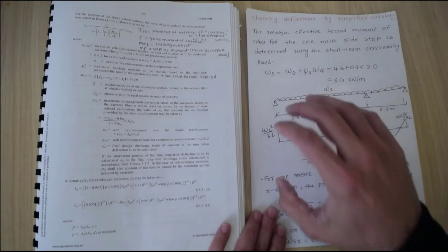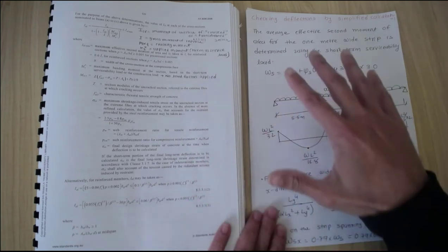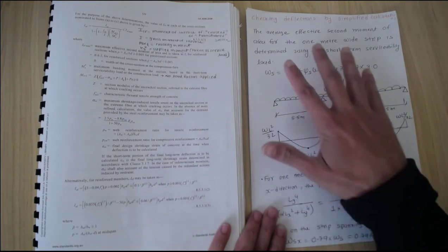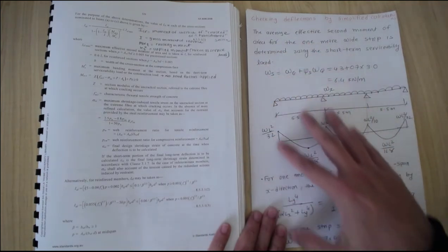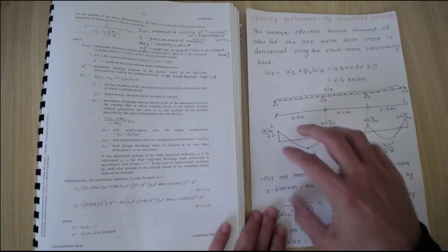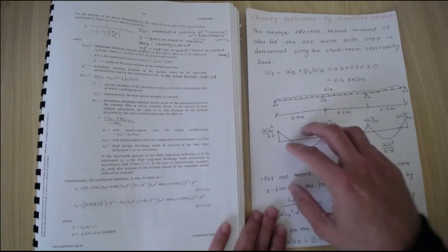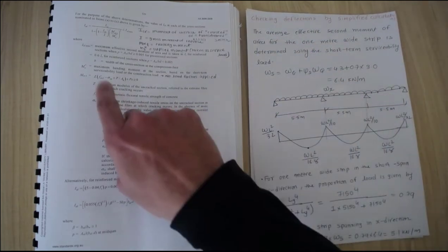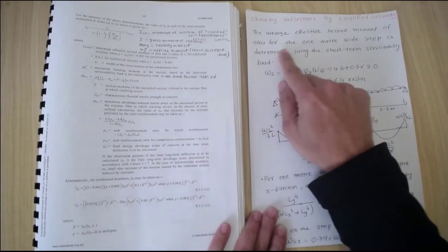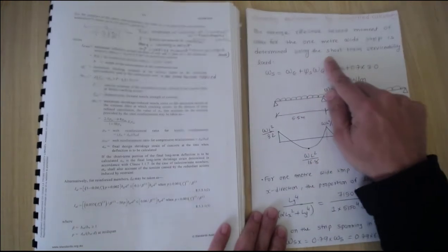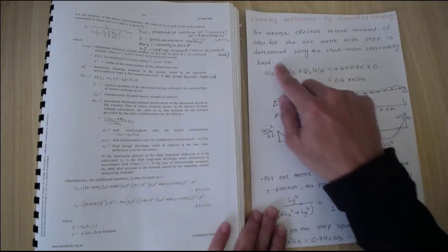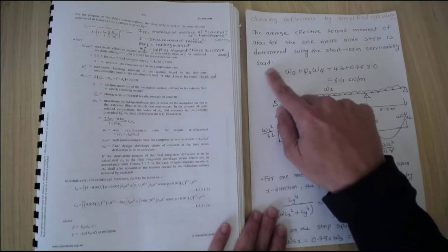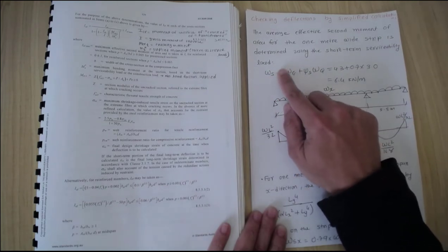I encourage students to watch the video for the deflection of beam, where I have a detailed discussion about each parameter that we use. Here I'm not going into great detail, rather I will just go through the main difference followed for the slabs. If you want to calculate the average effective second moment of area, I effective, for a 1 meter wide strip using the short-term serviceability load, please note that the W we calculated for strength cannot be used here in serviceability. We can't use this factored load.